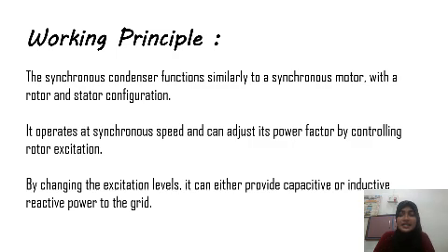And this is the working principle of the synchronous condenser. The synchronous condenser functions similarly to a synchronous motor with a rotor and a stator configuration. It operates at synchronous speed. Its power factor can be adjusted by controlling rotor excitation. By changing the excitation levels, it can provide either capacitive or inductive reactive power to the grid.